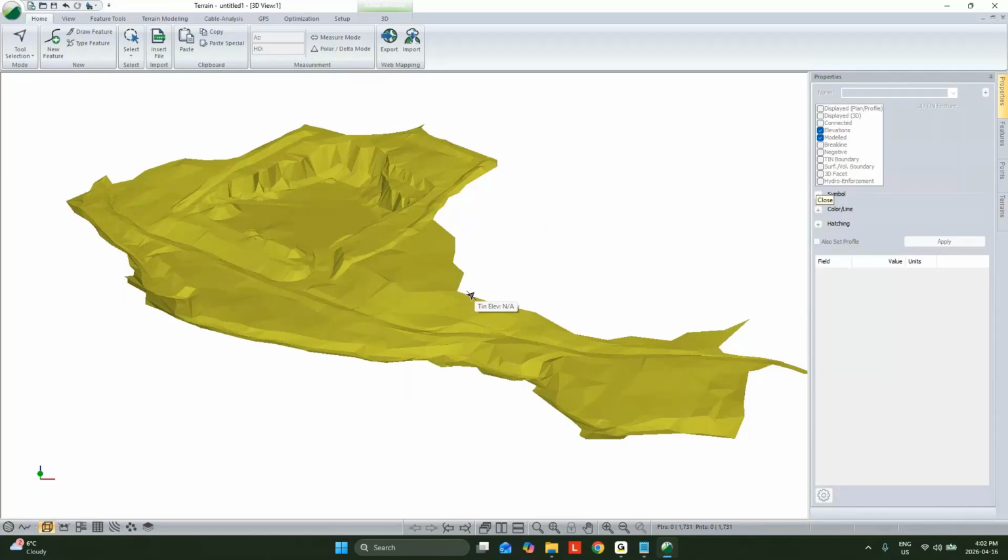Now that being said as well, LandXML is a fairly heavy surface, so I wouldn't use it as my default for, say, something like a big data set, landscape level surface. DEM is pretty concise, and there's not a lot of variability in where those triangles are going to be, since it's going to be limited by your grid spacing. So with that, we've got our alternative formats covered, and I'll pass it back to Aaron.